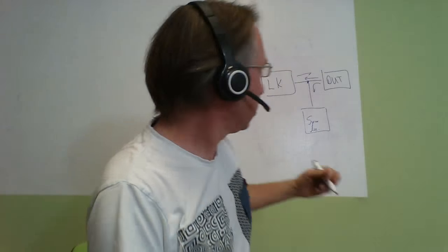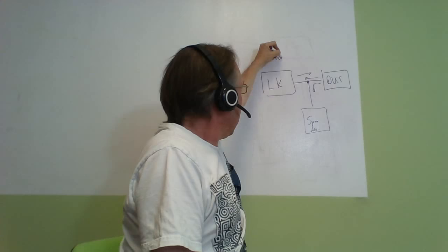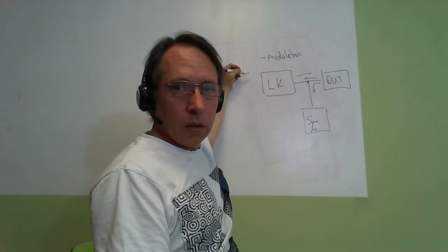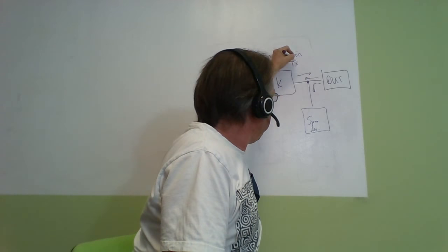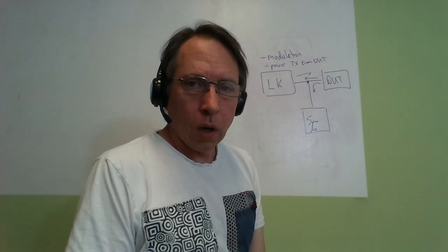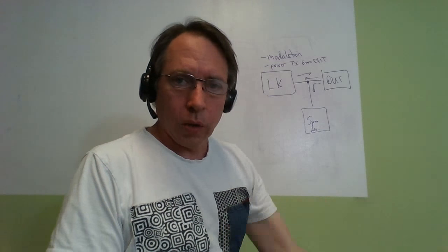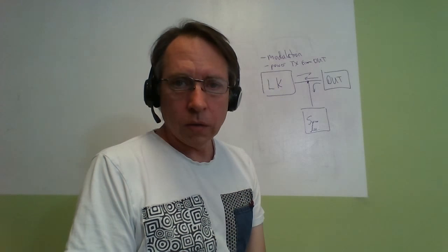And the LabKit has some special features to help you support this type of thing. One is it allows you direct control of the modulation on the uplink, and the other is it allows direct control of the transmitted power from your device. So you have direct control over power, you have direct control over the modulation type, and under those conditions you can drive the device under test into different extreme cases to see what's actually coming out of it.